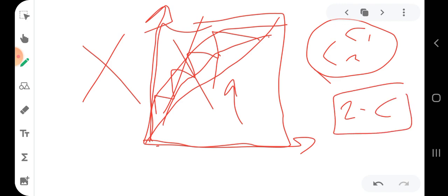But the question here: can we use these equations for multi-components for 2 components only? The answer is yes. Why not? It's okay. You can use these equations also to get an approximate solution for a binary mixture. There is no problem. But you cannot use graphical methods to get a solution for multi-component distillation.